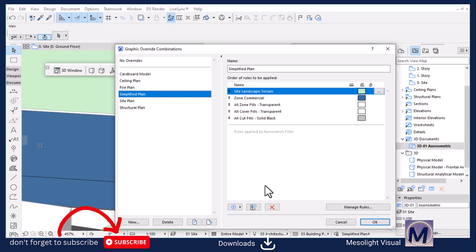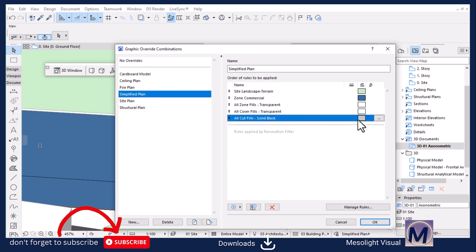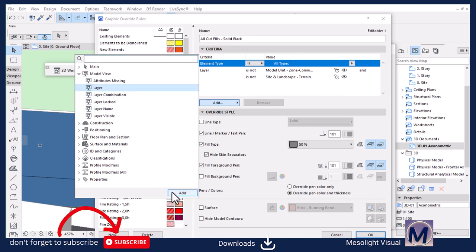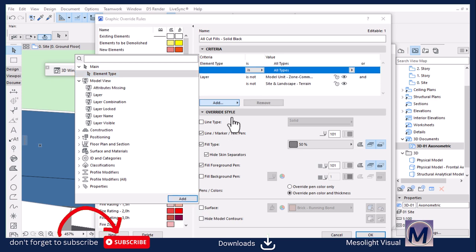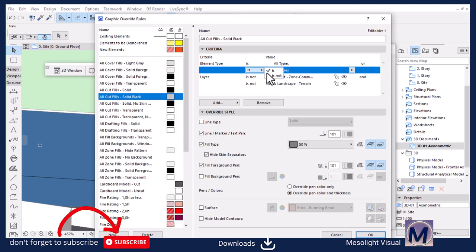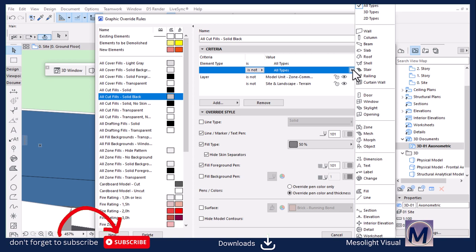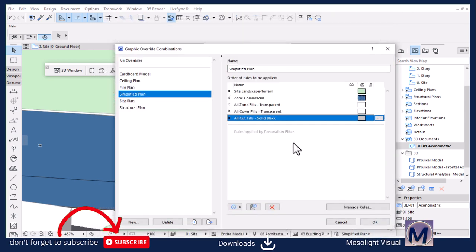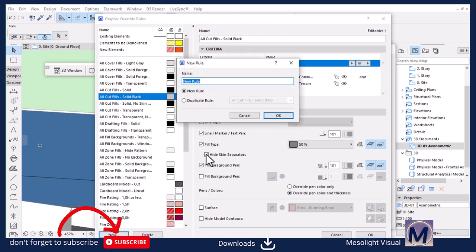So go back, and then under all cut fills, let's say edit it, and then let's add a criteria for the fills. And then no, this time around we're not going to use a layer, we're going to use element type, because it's a fill. Let's say it's not, and then the value is going to be the fill like that, and then hit OK. And then from here we're going to go to manage rules to create a fill outline rule for commercial.